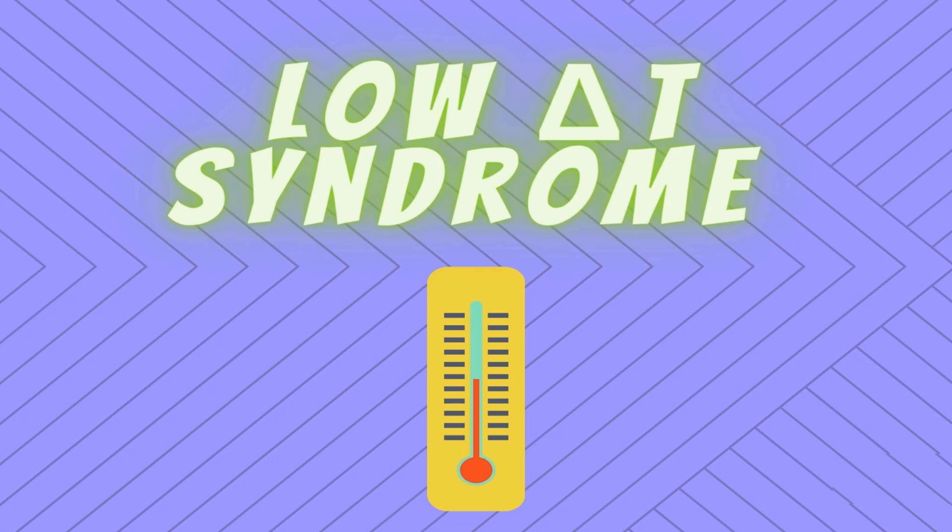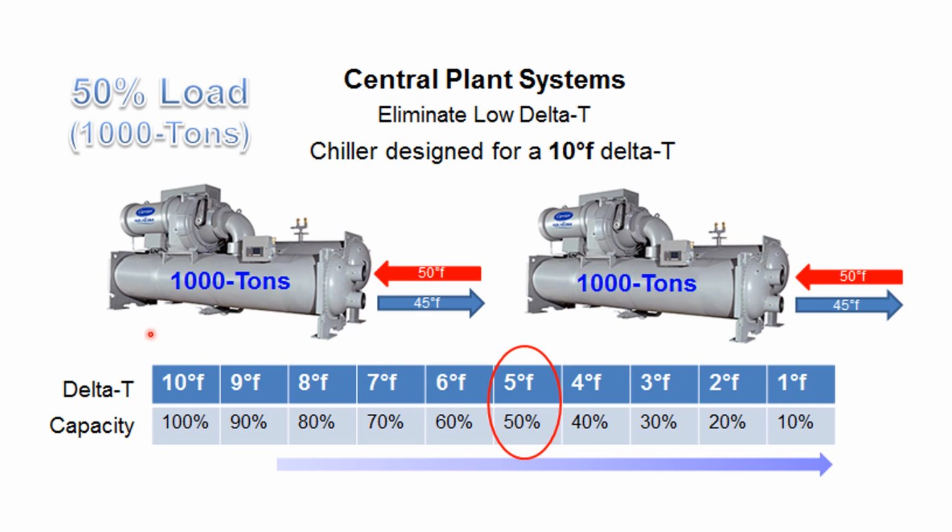So let's start. Here you can see there is a chiller of 1000-ton capacity, which is designed for 10 degree Fahrenheit of delta at 100% of the full load capacity. 10 degree Fahrenheit means 12 degree centigrade inlet and 7 degree centigrade outlet, which means 5 degree centigrade. So if the chiller is working at full load for 5 degree centigrade of delta, 10 degree Fahrenheit at full load condition, but because of functional issues, if the chiller is operating at part load conditions, it is becoming inefficient.